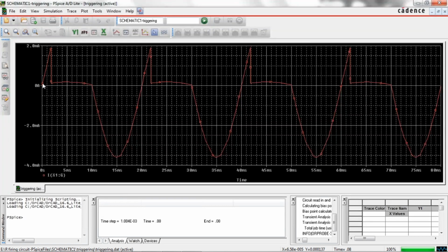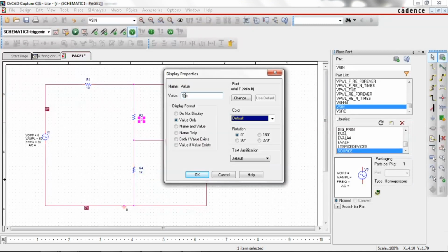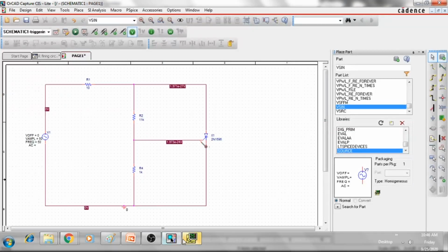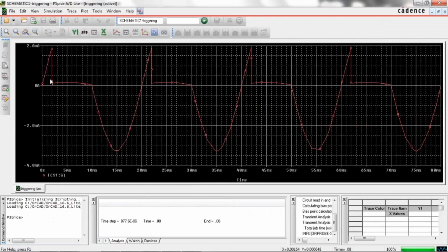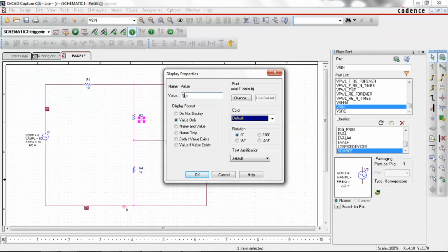So now this point should come somewhere here, which means the current should increase slowly in this way, so that the point comes here. Slowly the current should reach that value. How? We'll increase this resistance, we'll make it 11k, so the current reduces. See, earlier it was at 1.8, now it is 2. Still I should increase. I will make it 14k or 15k, we'll see.